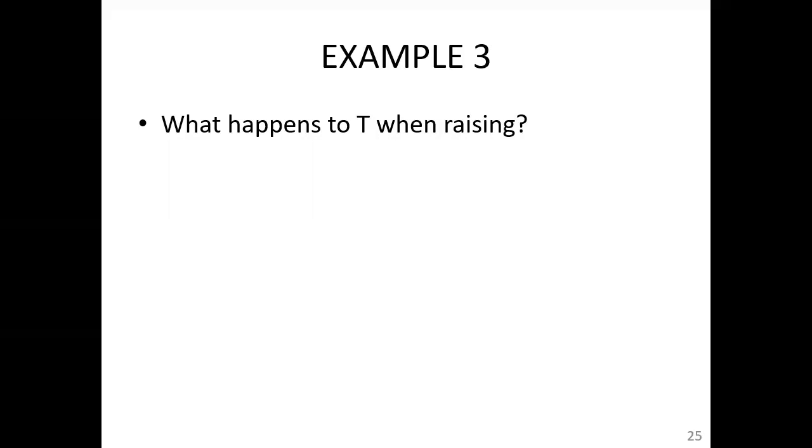Once this panel starts moving, you now have a drag force on it. The frictional resistance between the physical surface of the concrete and the fluid. And that drag force opposes motion. So for example, if we're pulling it up through the water column, the drag force is in the opposite direction.